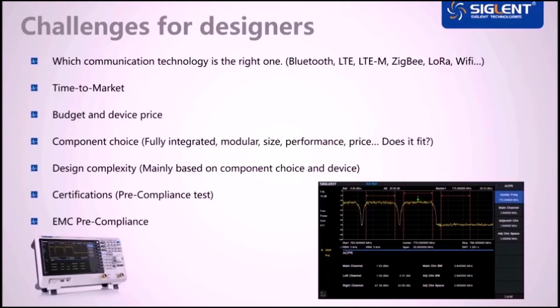All in all, in the end, it doesn't matter whether you don't get an approval because of a failed EMC or a failed communication standard test. If you don't recognize mistakes in time, it's possible that you have to take a step backwards, sometimes back to the choice of components. To avoid this, you should test and measure in every design step, especially when you're integrating new technologies with constantly changing requirements.